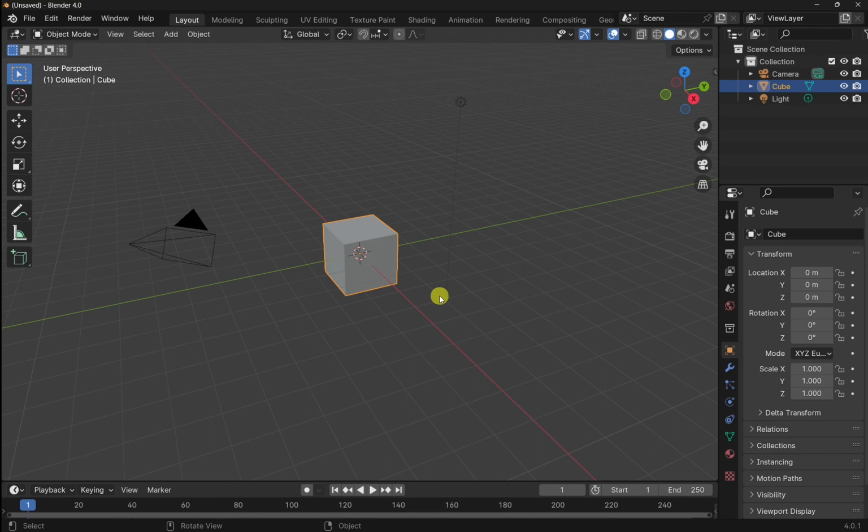Today we're going to be looking at basic movement in Blender, both using the Move tool and the keyboard shortcut G, which is a keyboard shortcut for grab. We're going to be looking at locking the axes, removing an axis from the selection so we can move along, say, the XY or the XZ and remove a single axis from there. We're going to be looking at exact placement and also around the 3D cursor.